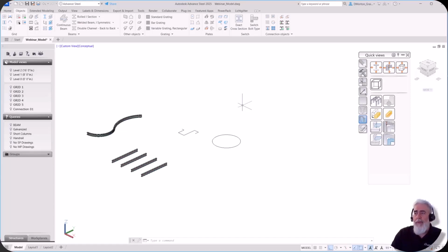The third tool for placing in a beam gives us the ability to create the shape ahead of time that I want to use. This one here is going to be the folded plate. It's right there. That's rather folded beam, not folded plate. If I left click on that, it says, first of all, pick my polyline, my circle, or my arc. So we're just going to do the polyline first. And there's the shape that I specified.